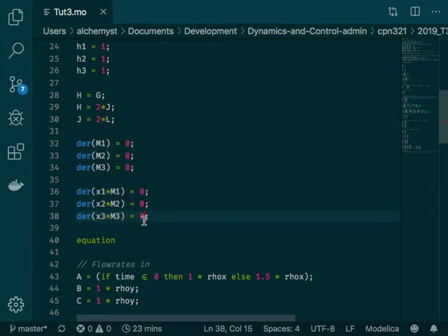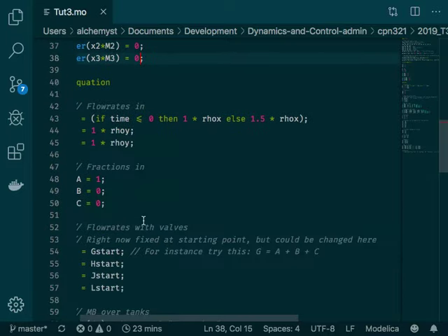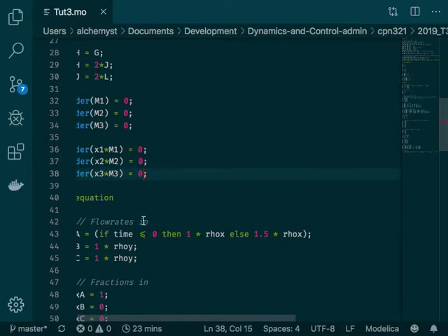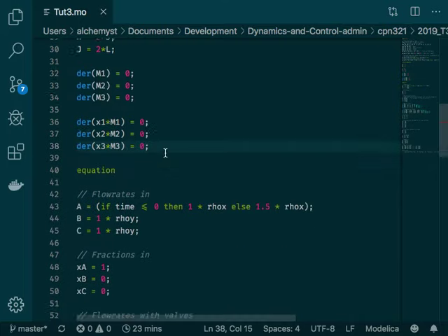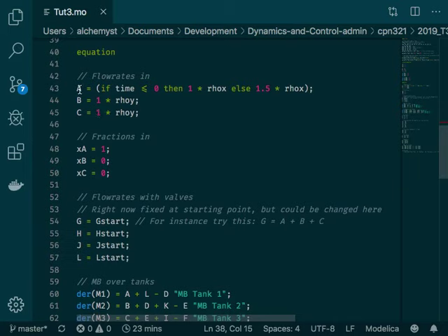Okay? These equations are added to the full set of specifications during initialization of the model when Modelica runs the model. And so it does a solve for the initial equations first. It then uses those parameters, and it will use these equations to find K1 and K2, as well as the initial values of all the flow rates that are specified later.